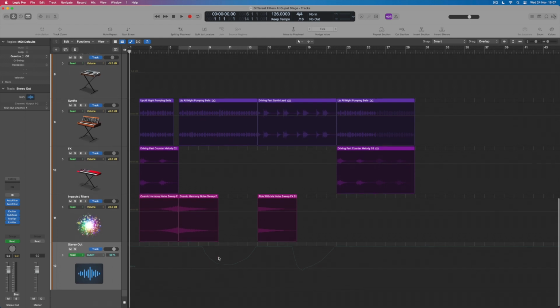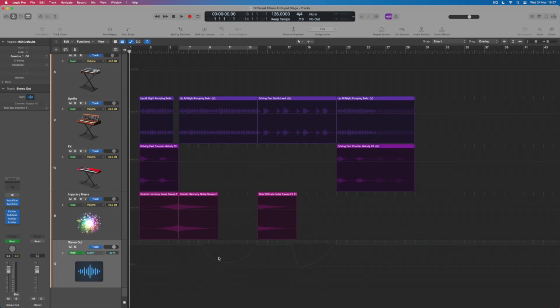So in this context, my high pass filter is going to do the opposite of what the low pass filter did. What it did was to let bass content through all of the time, and it varied the amount of high frequencies we could hear. Now what we're going to do is to always have high frequency content, and we're going to vary the amount of bass that we can hear. So in other words, as I adjust the cutoff frequency, what we're going to get now is shaving out the bass end, getting rid of it, carving holes in it if you like, before we can then recover the bass and have that come back in. So with these 2 filters working side by side, we might be able to produce some really interesting effects.